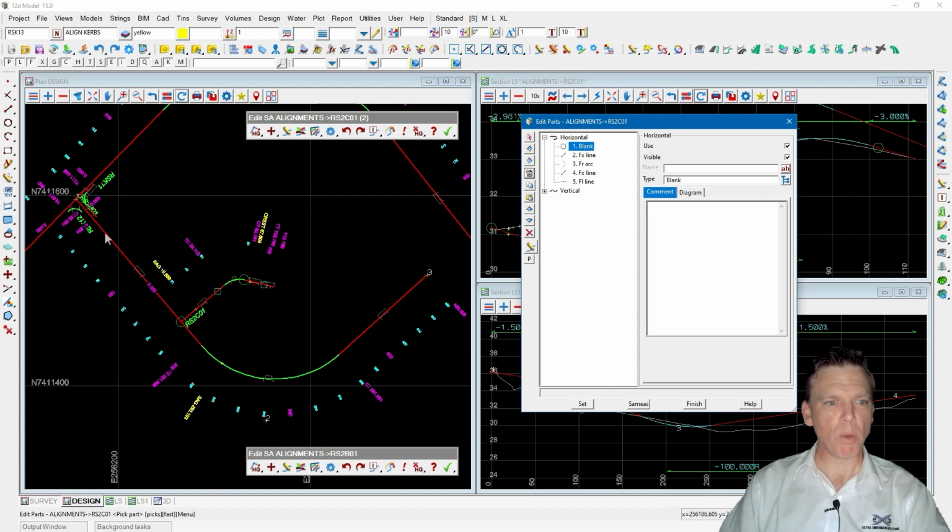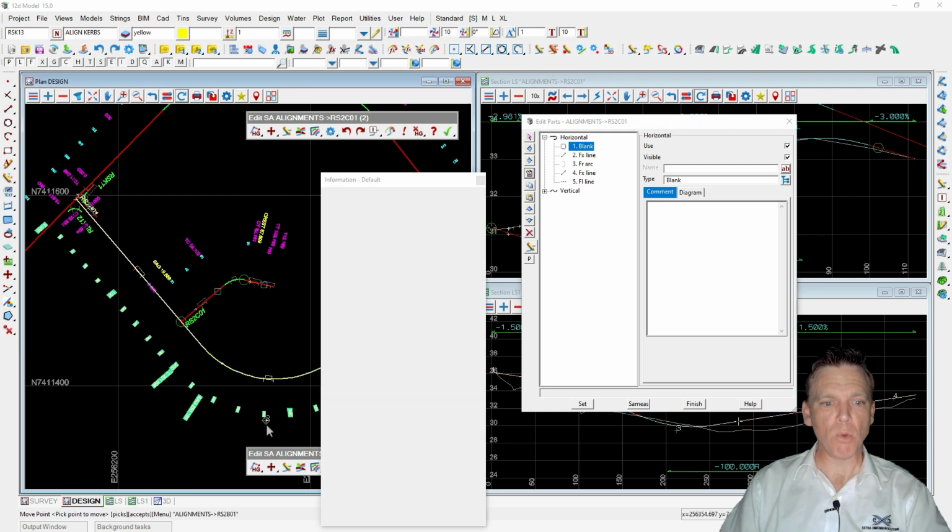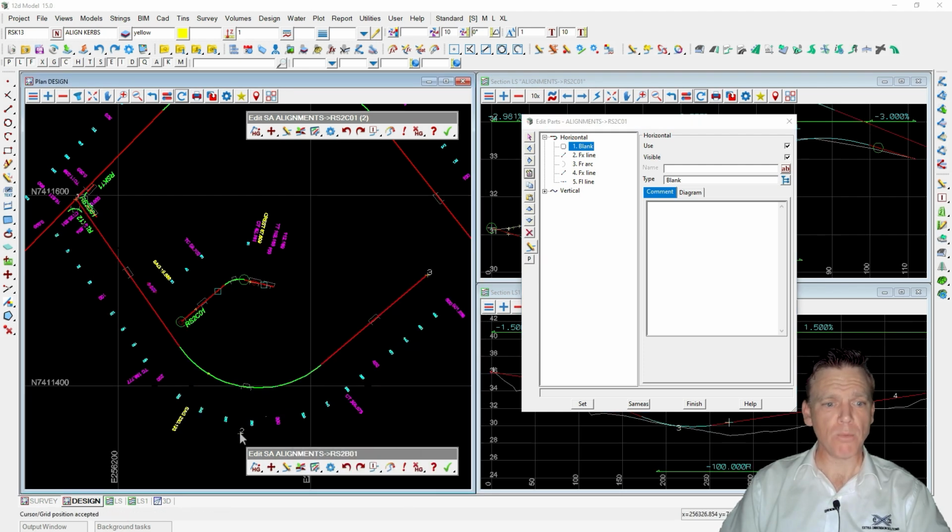I've basically been wanting to put in a fixed line down there so that I could find where the two would intersect. That way, when I move this coordinate around or move the road in this direction, that line would essentially be those two points, that line would be copied or referenced, and 12D would then go down and find where the two would intersect.